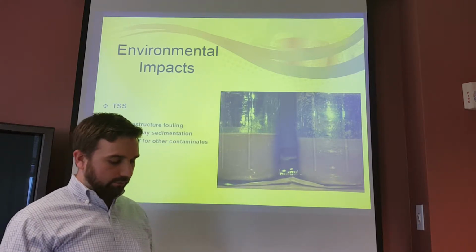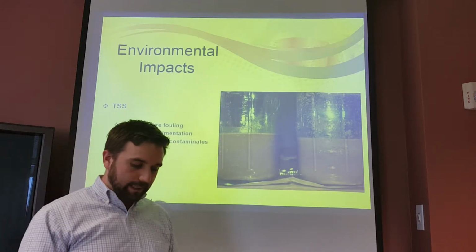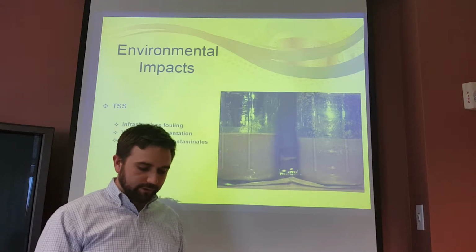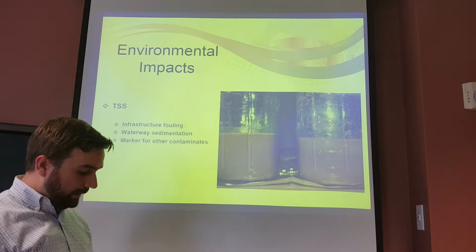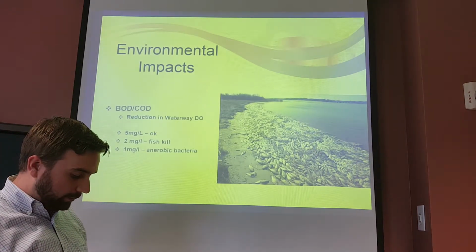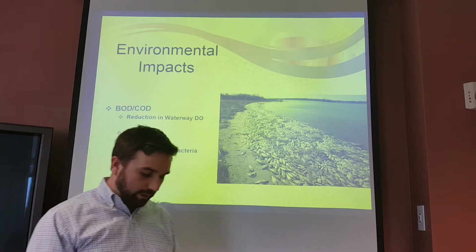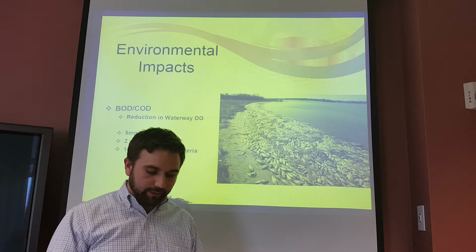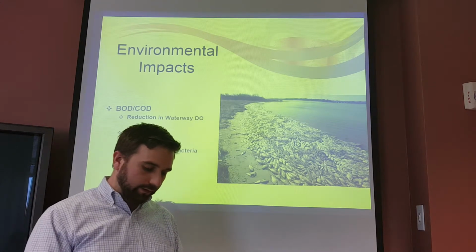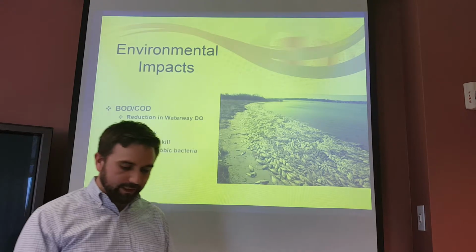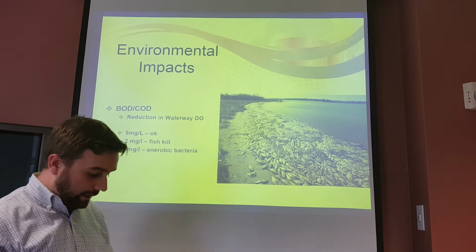So I want to talk about some environmental impacts of these contaminants. TSS is generally a marker for other contaminants, such as BOD. However, a high TSS can clog infrastructure such as municipal sewer pipes or on-site septic systems. BOD and COD are regulated by the NPDES program due to their strong effect on natural waterways. A high BOD discharge will cause bacteria to eat up the dissolved oxygen in the waterway, which can choke out aquatic wildlife and allow for the growth of anaerobic bacteria.